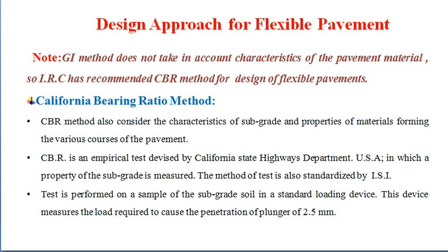The design chart shows that a material with a given CBR requires a certain thickness of pavement layer cover, and a higher load needs a thicker pavement layer to protect the subgrade. That means if there is an increase in the design load on the pavement, there is a requirement to increase the thickness of the pavement simultaneously.